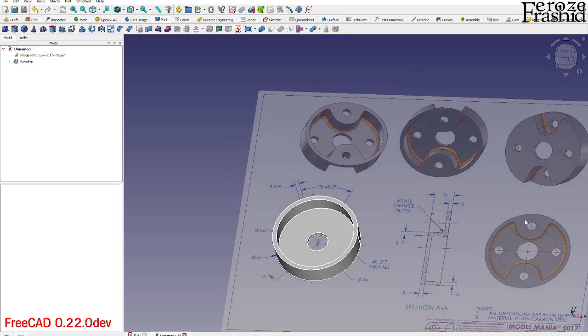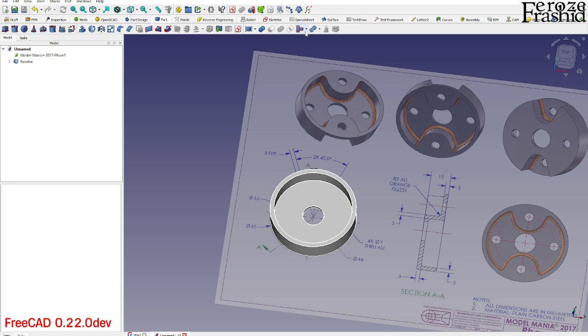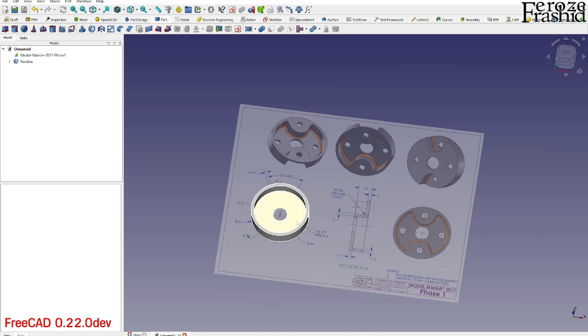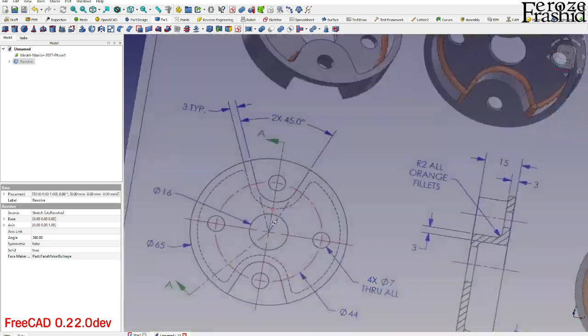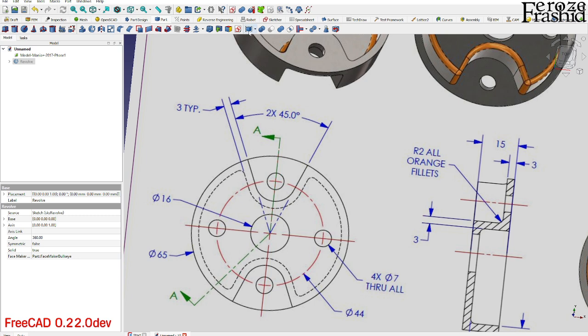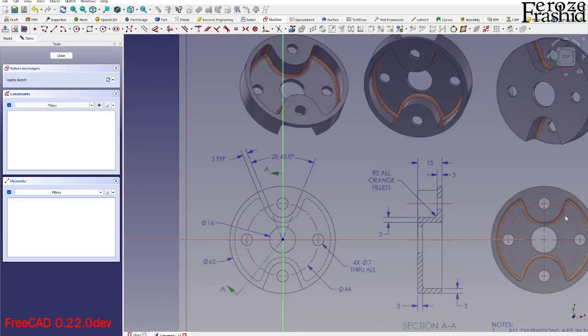My idea is to build one of these units, embed it into this using the combine tool, and then replicate that 2 times. So let's see if we can do that. I want to build this one depression in there. I don't want to attach it with anything. I want to do it on the XY plane, and the offset would be on top of that. So it would be a 15 millimeter offset, which is the height of this wall.